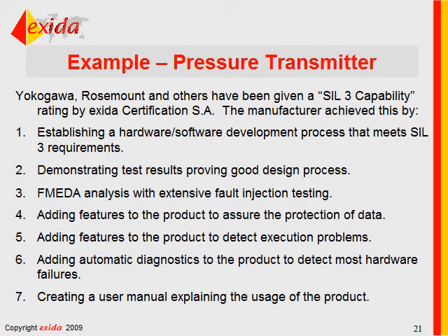What happens if a memory drops a bit in your transmitter? Does your transmitter detect and correct the problem, or does it simply give you a bad reading? If it's been certified, it's highly unlikely to give you a bad reading. The manufacturers added features to detect microcomputer execution problems. That microcomputer stops executing properly. There are diagnostics, hardware and software, that will detect that.